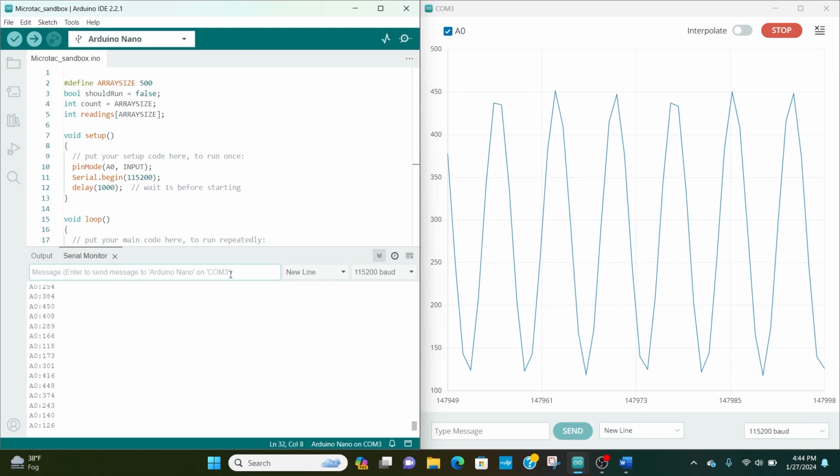This 10 kilohertz sample rate might just be way too low, especially when I throw in other elements in the code that the microcontroller is going to have to deal with. I may end up with a significantly lower than 10 kilohertz sample rate. So if I have no choice, I might have to go to a higher power microcontroller, or something that can give me a higher sample rate. But we'll see when I get to that point in the project and actually get the entire audio chain connected and see what it sounds like.